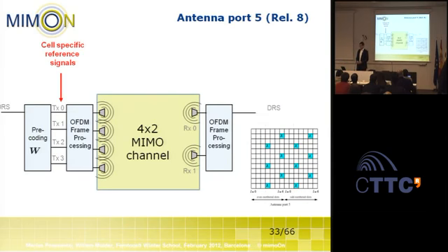So let us take a look at how this non-codebook based beamforming is supported in LTE. It was first introduced in release 8, where non-codebook based beamforming was only supported for a single stream sent to users. It was first designed for transmission to cell edge users, to steer beams towards those users to increase the cell coverage. For this, if we design our beamformers freely at the transmitter, we have to have some means to inform the user equipment about the choice of our beamformers.